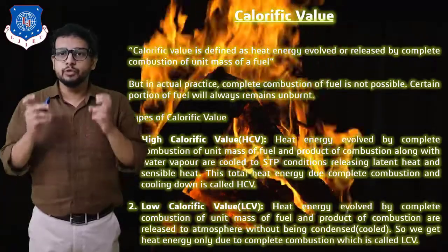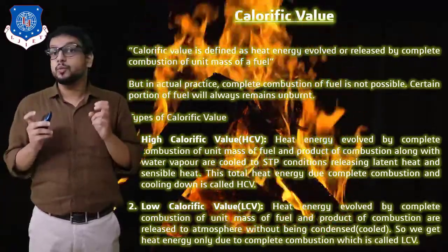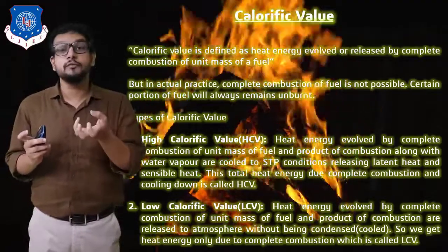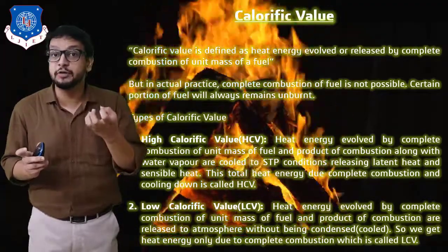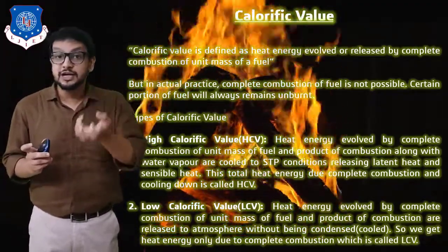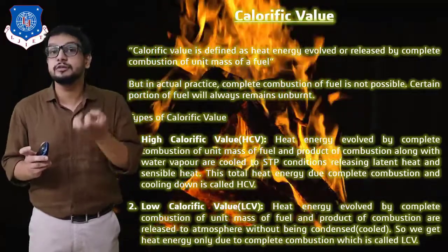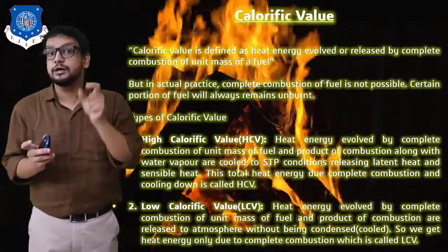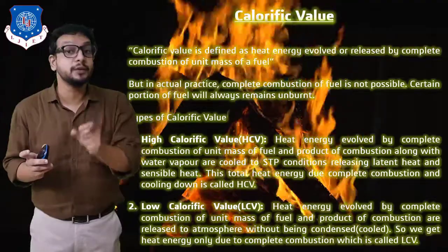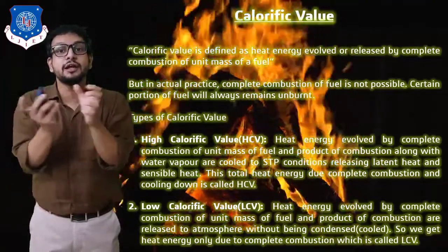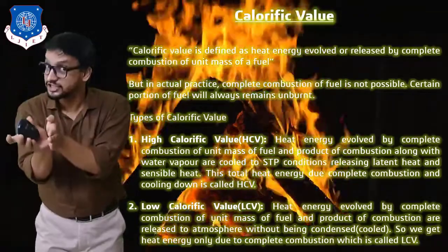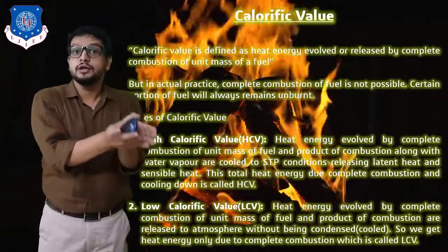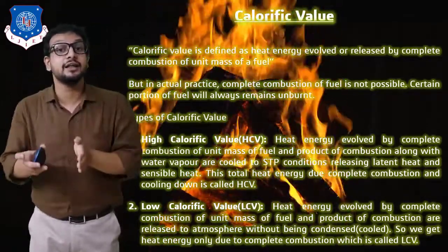So when this water vapor produced along with the products of combustion is condensed, meaning cooled down, what is going to happen? It is going to be converted into liquid form, right? And when it is converted into liquid, heat energy will be released from the water vapor. That heat energy released, along with the heat energy produced by complete combustion, the summation of both, that is the heat energy released by condensation of water vapor plus the heat energy released by combustion of fuel, contributes to the high calorific value.